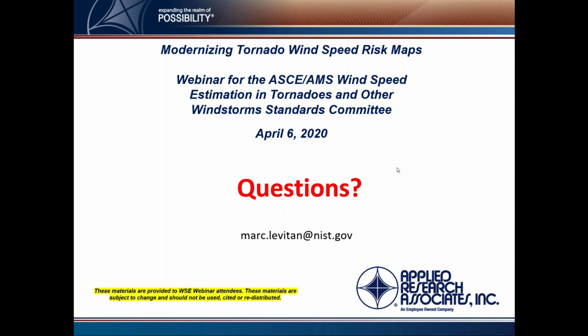So, yes, we did specifically look at the hurricane-spawned tornadoes. They did have an effect on the climatology, as all the tornadoes in the database do. The modeling that's done to develop these wind speeds is very different than what's done for hurricanes. Of course, we have so much more actual data and so many real measurements of hurricanes. The number of hurricanes is 2 orders of magnitude less than what we have, and so it's a much different modeling process that's done to develop the hurricane speed maps that are used for the ASCE 7 standard.